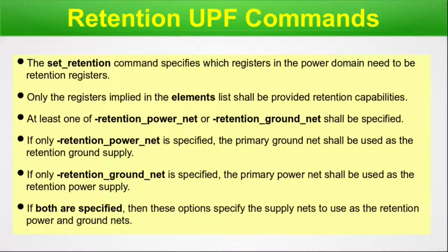So guys, it is very simple: this particular command has to specify along with it any one of the retention power net or retention ground net. Okay, so this will instantiate the retention cells or flops into your design through the UPF text. We are done with this particular slide. Let's move on.